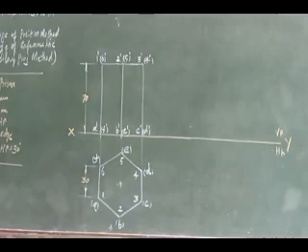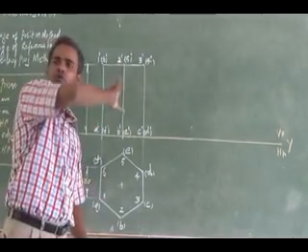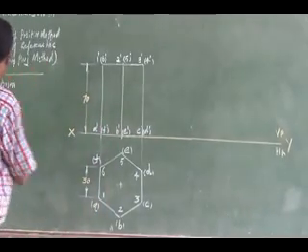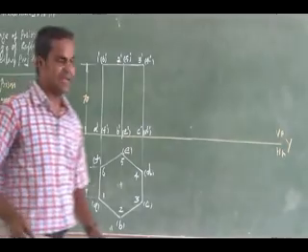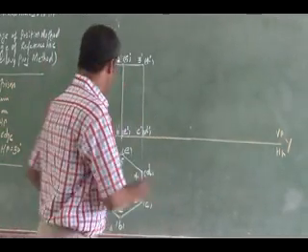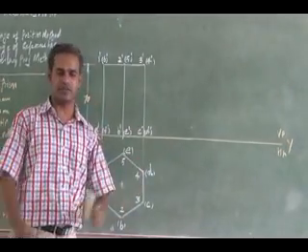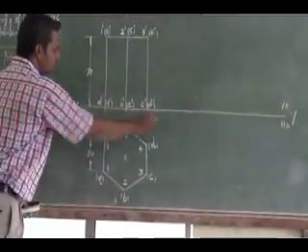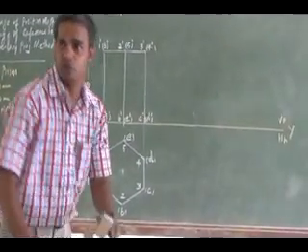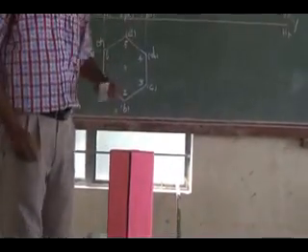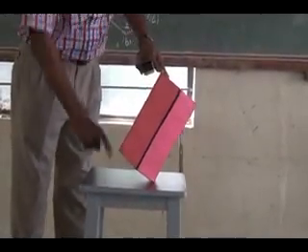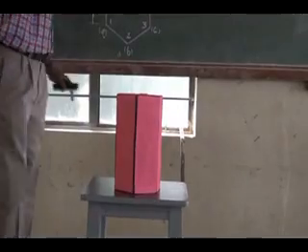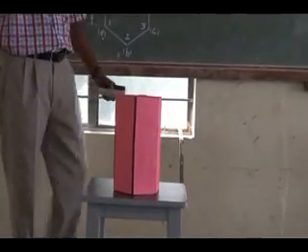So I have to tilt the final front view to 30 degree inclination. Okay, the axis is 30 degree inclined. So listen, axis is 30 degree inclined. What you can do, just which is going to be my resting corner. If I tilt, so you see here in this orientation, this is the base, ABCD base in the bottom, which is on the stool, right? So if 1, 2, 3 base is on the top, if I tilt it, okay, so ABCD base, the edge will be on the ground. What is that edge here? CD.